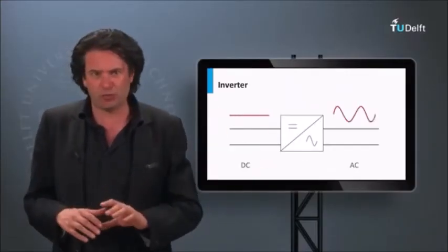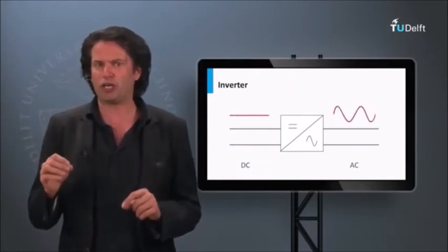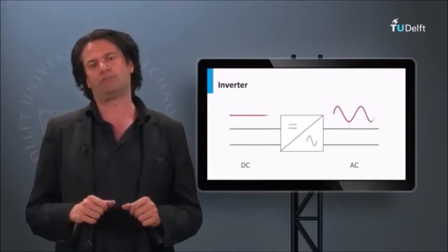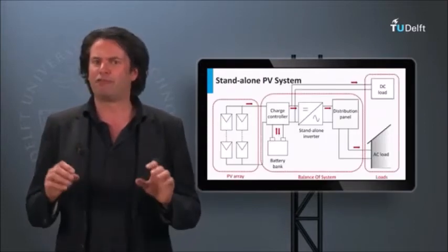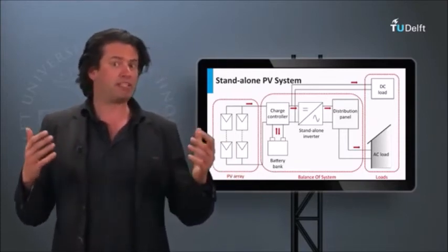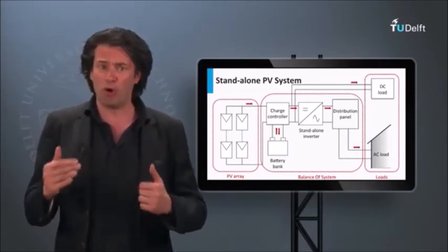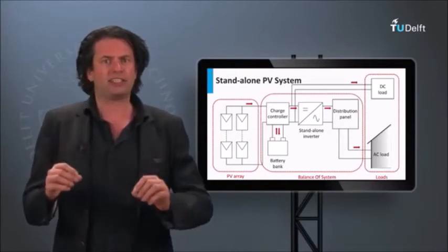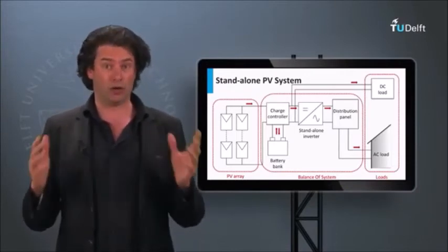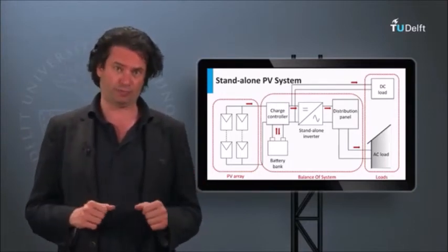Given the time constraints, we will not go into the internal circuitry of the inverter, but we will talk about the features of the solar inverter and its application in the modern PV system. Now, inverters could be classified based on their size, mode of operation, or implementation topology. Here I will talk about the classification based on the mode of operation. Under this, the inverters can be classified into three broad categories: standalone inverters, grid-connected inverters, and bimodal inverters.